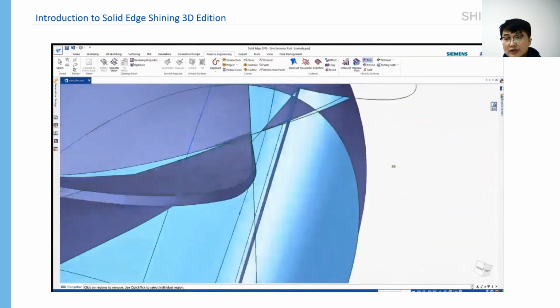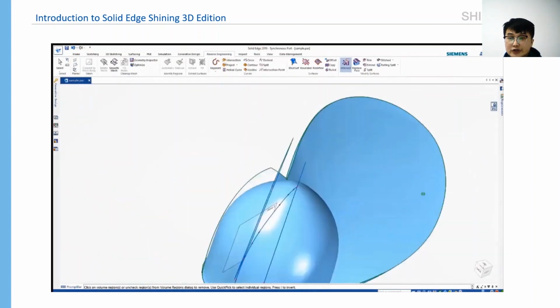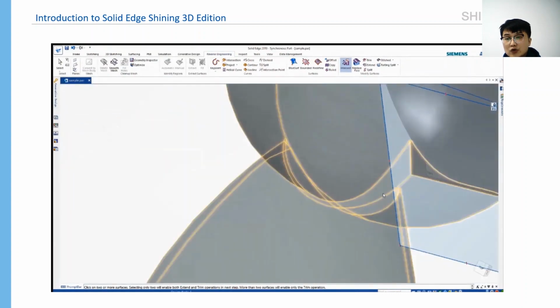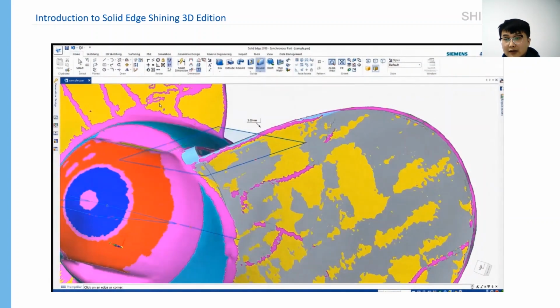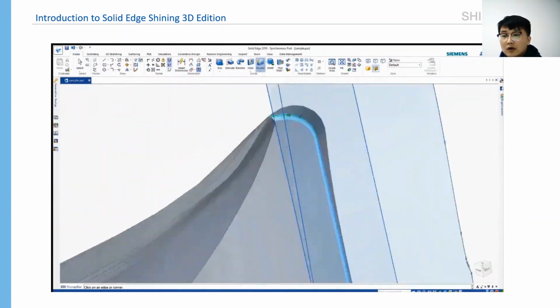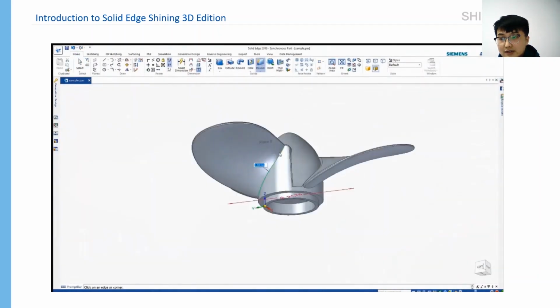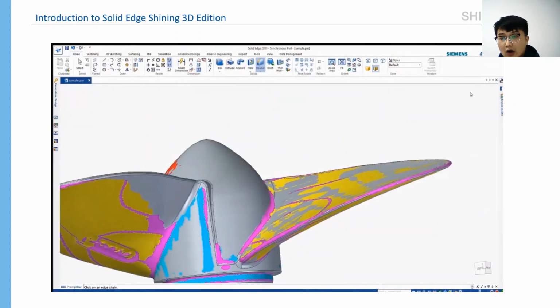And you need to do some trim work after you fit all the necessary features with those surfaces, so that you can turn your surfaces into a solid entity. So here, we almost got the blade, and you just need to do some further processing, like patterning the blade into 3 pieces and adding some rounds on the edges of the model. It looks very easy to do the reverse engineering work in the software, right?